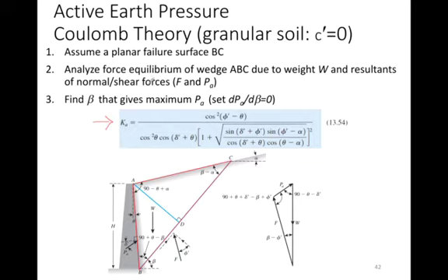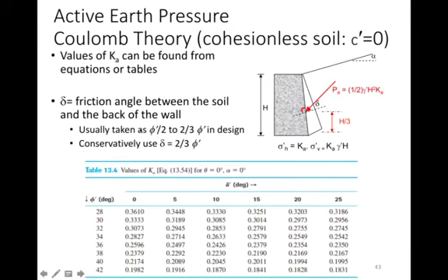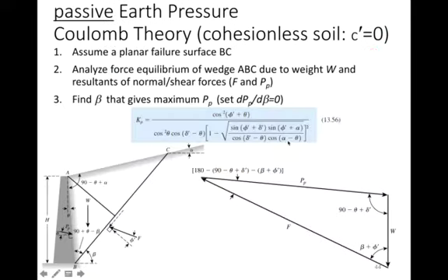Here's the assumptions of how it was set up. But basically, the idea is you would use this Ka in the equations that you're going to use. So here is the table. Once again, you can take into consideration if there is a slope or inclined plane behind the wall, and you can calculate your Kas and ultimately your horizontal stresses.